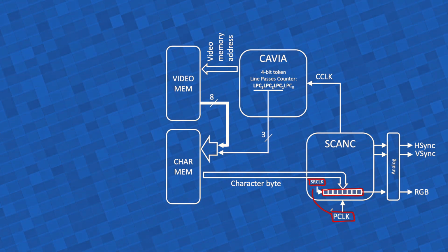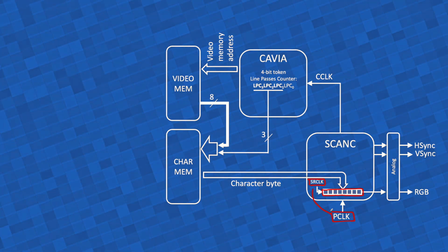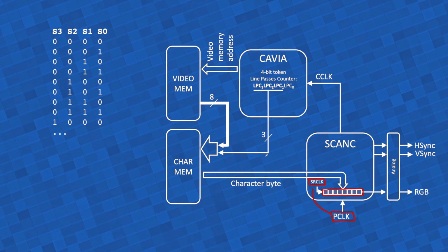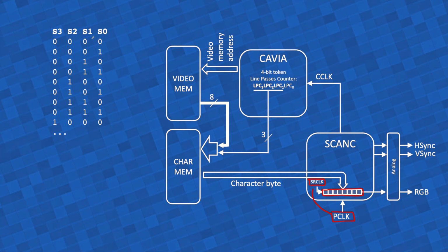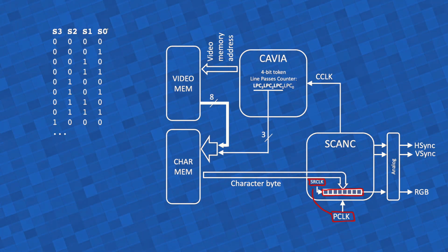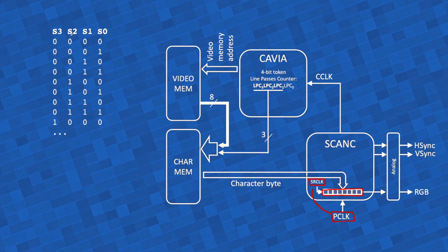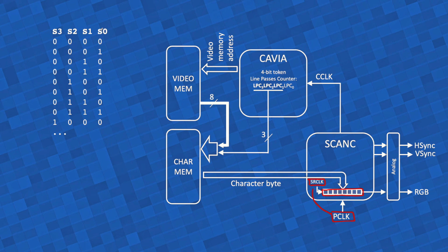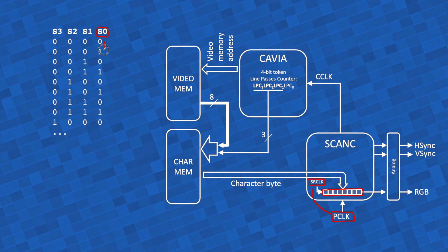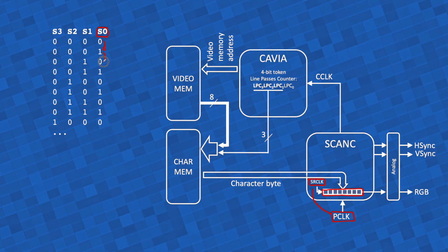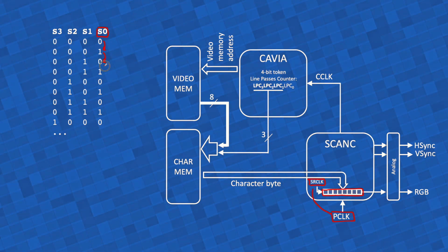That was the challenge. And we approached this challenge by building a 4-bit counter which would work as a clock divider. So the idea would be, okay, if I have these 4 bits counting from S0 to S3, you see here that S0 changes state every time there is a clock tick, and the clock for this counter is the pixel clock.